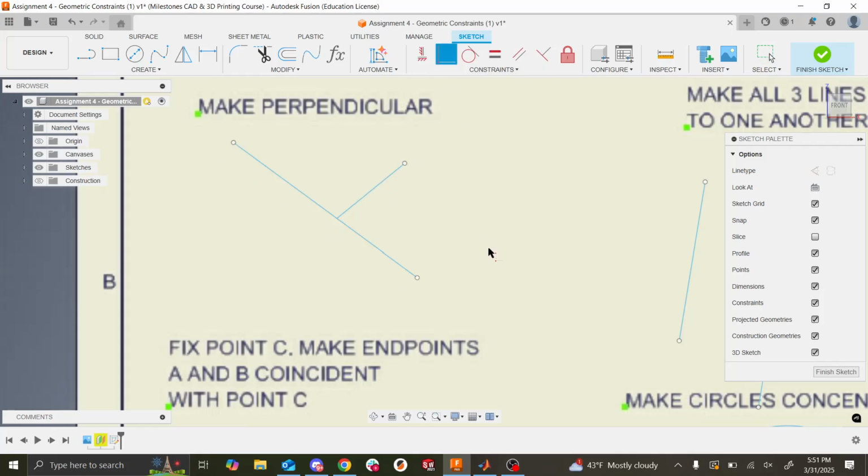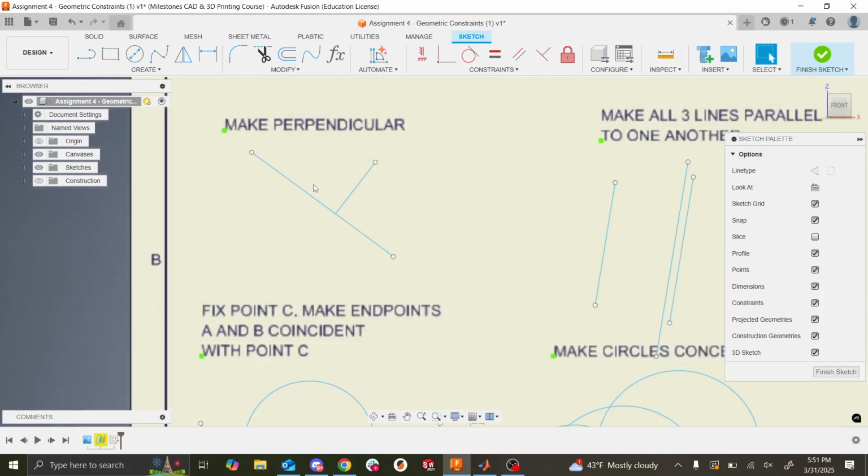So one of the things I like to do, I find it faster a lot of the times to just delete something, like delete a line, and redraw it and then reapply the constraints. Especially if you've gone really deep, you've made 5 or 10 lines later, you don't want to Control Z all of it. So a lot of the times I just delete it and then make a new line or a circle. Obviously, it depends on use case, but yeah.